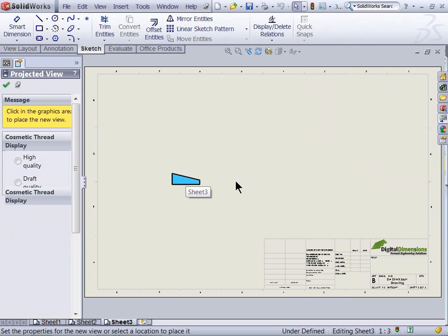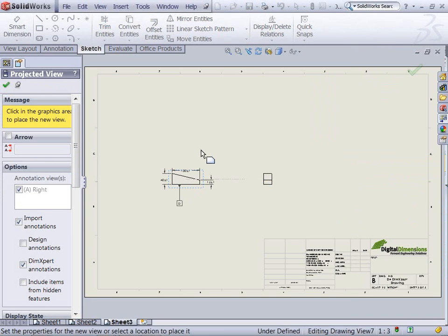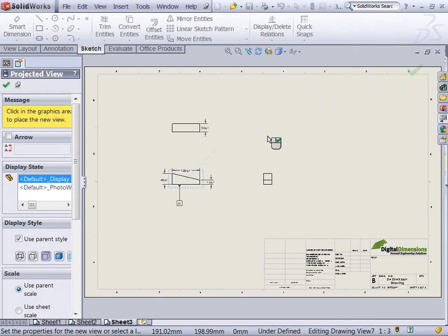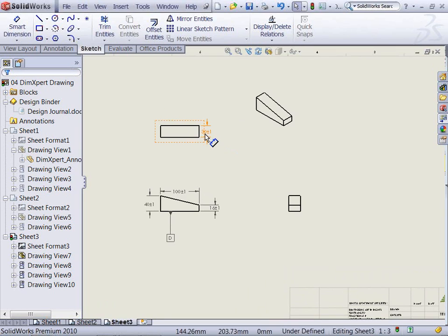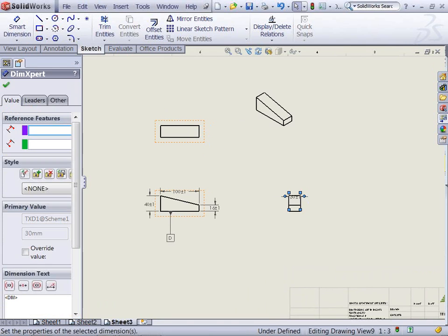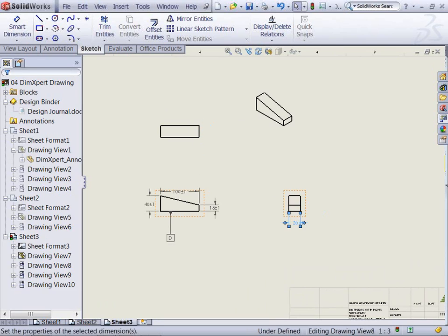This is actually going to be a lot more useful than the model items if you did not control the original drawing, because I can still specify my datum structure, I can fully define my part, and then have the ability to move dimensions from view to view using Shift drag, and have some relationship between the drawing and the model.